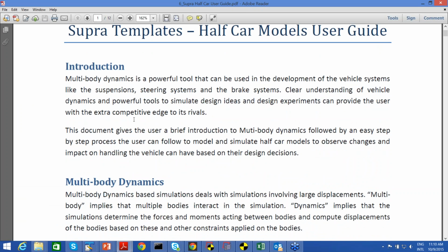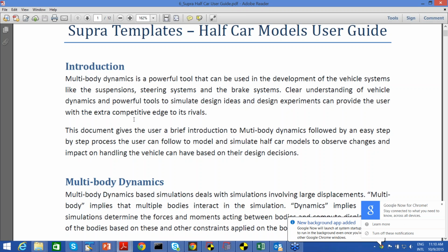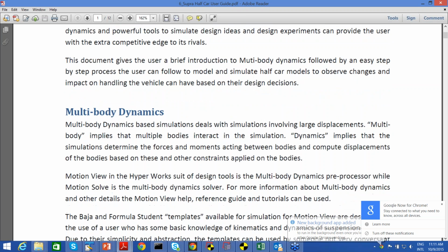In a vehicle component system, when you are interested to study the suspension systems, steering systems, braking systems, and overall behavior of your system with your physical inputs of springs and constraint inputs, hardpoint locations, once you build that virtual model, you would like to understand how your vehicle is behaving. So we will build those configurations here, and we will observe the vehicle behavior.